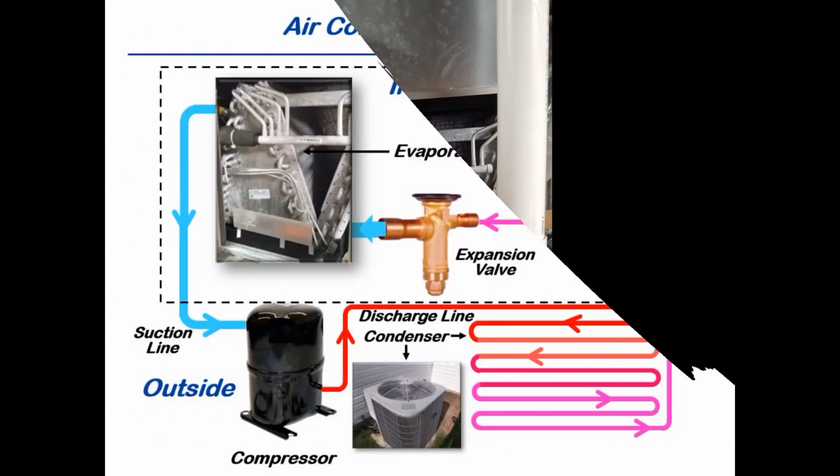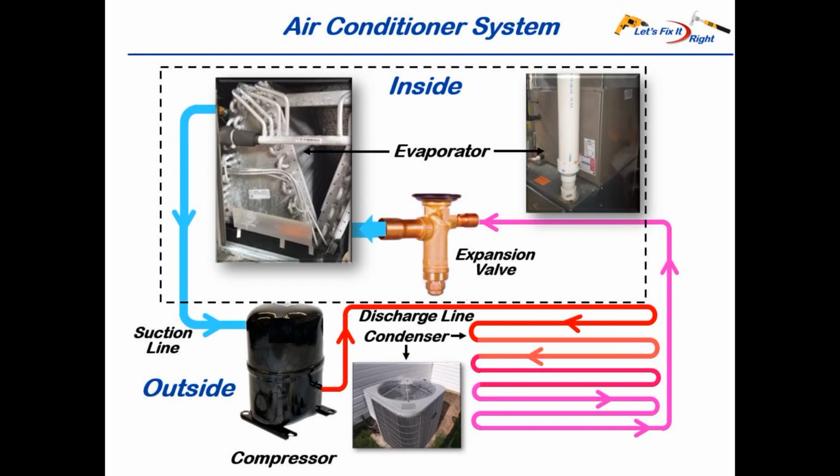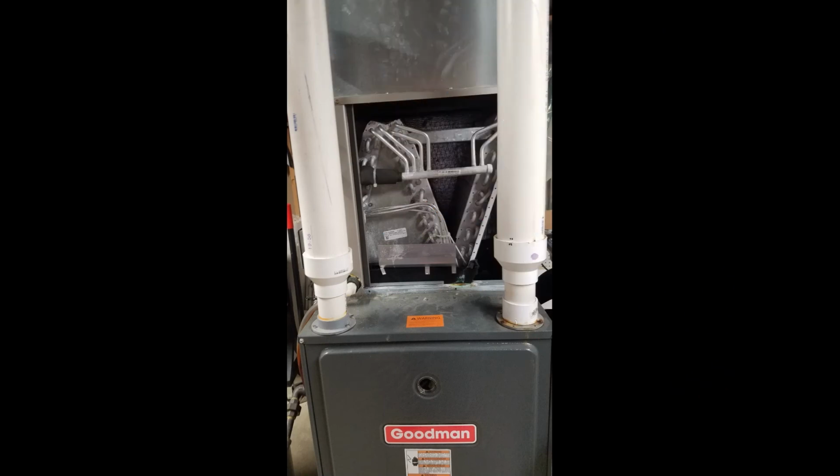If you have a slow leak, an HVAC technician can refill it, but if he does not repair the leak, it will leak out again over time and your AC will eventually fail to cool again. In addition, an HVAC technician can load dye into your system to determine where the leak is coming from and in some cases permanently repair the leak. The majority of leaks occur in the evaporator, which normally needs to be replaced because the evaporator joints where leaks occur are extremely difficult to solder.